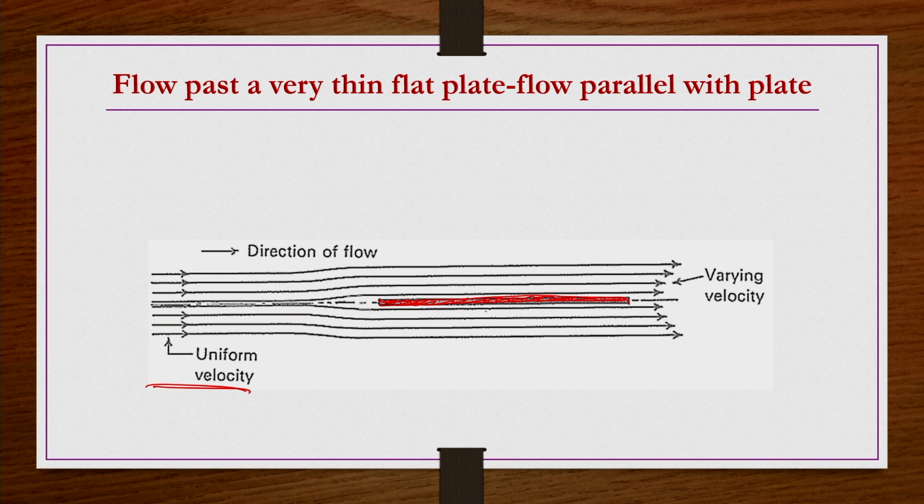The force this edge receives because of the fluid flow is going to be very small, whereas the force this surface receives because of the fluid motion is going to be large. The force in this direction is the pressure component, and the force along this surface is the shearing drag. So the shearing drag, the wall drag, is more important and larger compared to the pressure drag here.